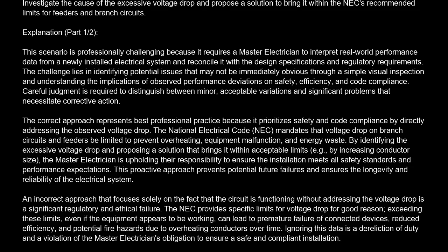The correct answer is A. Investigate the cause of the excessive voltage drop and propose a solution to bring it within the NEC's recommended limits for feeders and branch circuits. Explanation. This scenario is professionally challenging because it requires a master electrician to interpret real-world performance data from a newly installed electrical system and reconcile it with the design specifications and regulatory requirements.